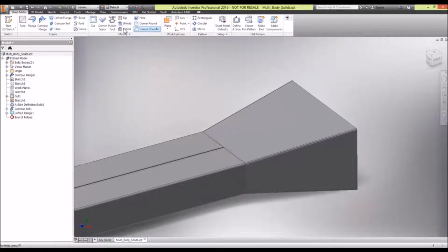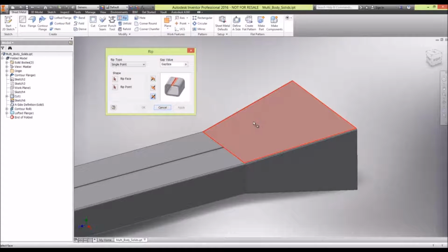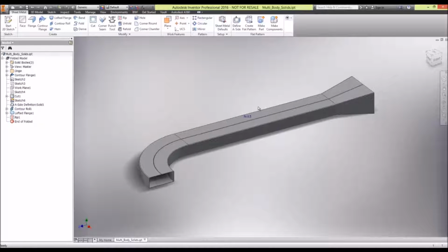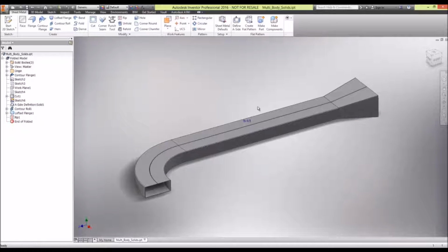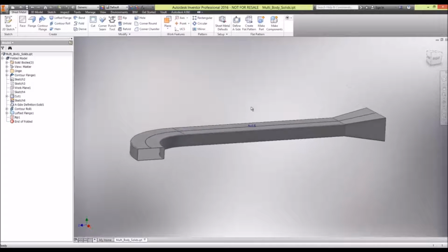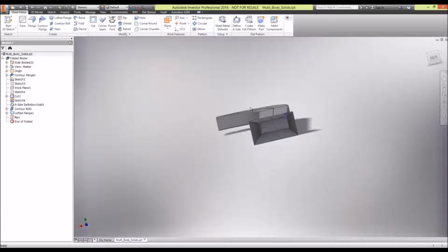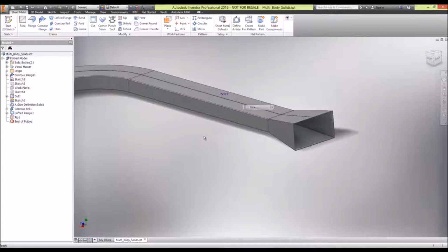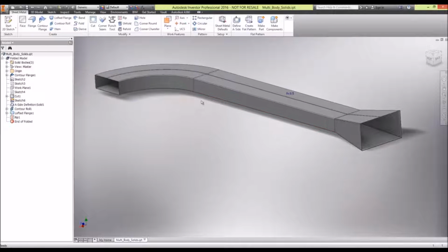One thing to remember is to make sure that we rip this, because we want to make sure that we can point to point on that face, midpoint to midpoint. So let's rip that up, so we'll make sure that we can unfold those. So I've got 3 parts here that all in effect react and behave linked together because of the power of multiple solids. What I'm now going to do is go and make components.